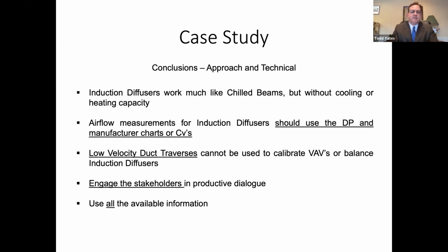But it's easy enough to calculate, because if your room temperature is 75 degrees and you're pushing 48 or 49 from the air handler, and your flow is roughly 50%, then you could measure that. But we did not directly measure that airflow. We did tinker with it a little bit. And if you're trying to measure with a sensor right there, there's just so much air movement. You can move it a little bit and it changes.